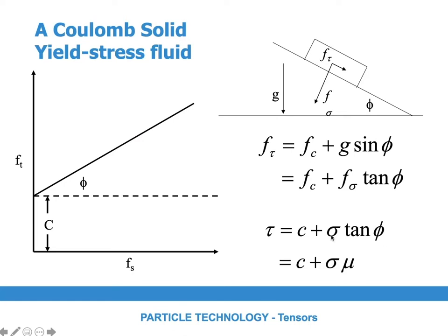We were talking most of the time about shear stresses and normal stresses, tau and sigma. There are also cohesive stresses, like due to glue or due to liquid or due to van der Waals adhesion, which make the material stick together. That is an additional stress. I didn't mention that one so far, but that one is actually the reason why we have this yield stress behavior.